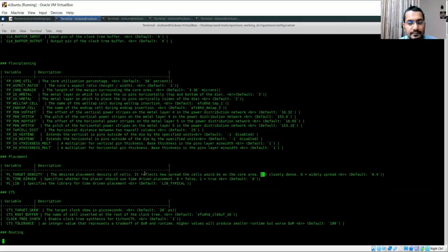you would first do the congestion analysis. Post that, as you move towards the design closure stage, you would want your timing constraints to be met. So first the design is constrained with respect to congestion. You want lesser congestion at the initial period. So these are the switches that we need to set for floor planning as well as for placement.